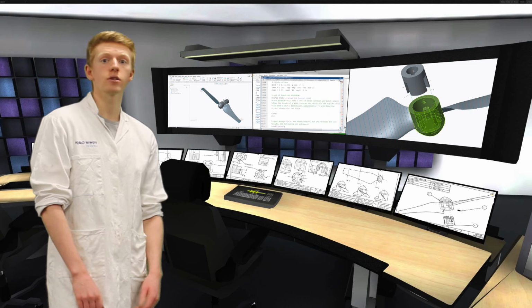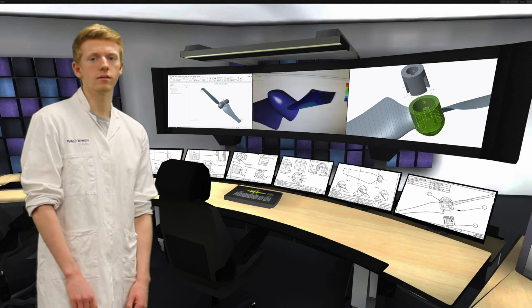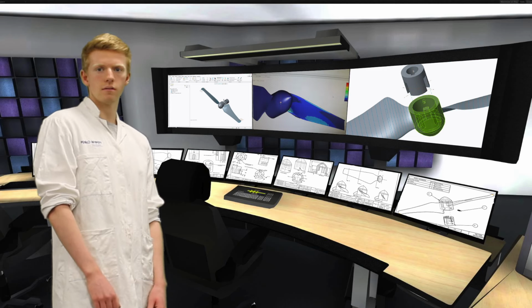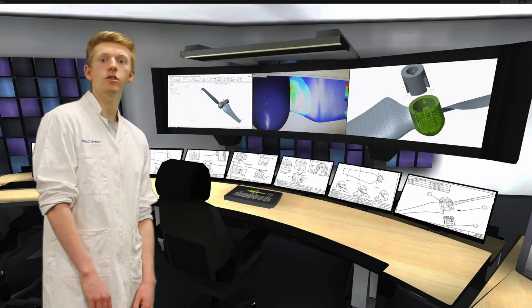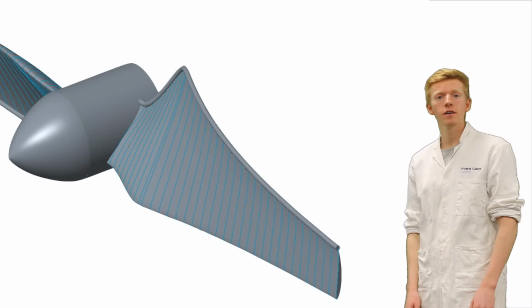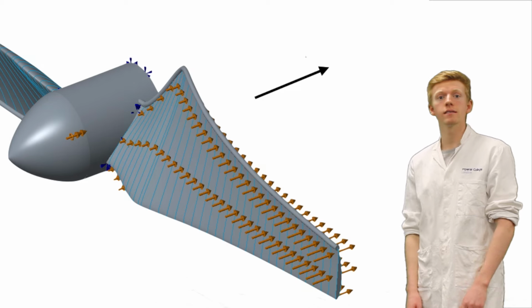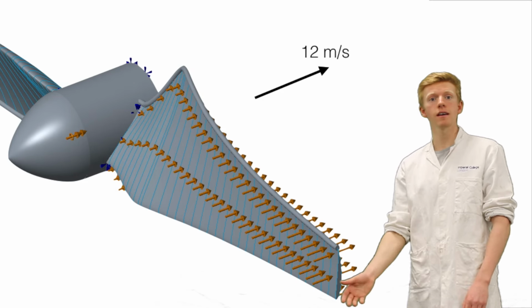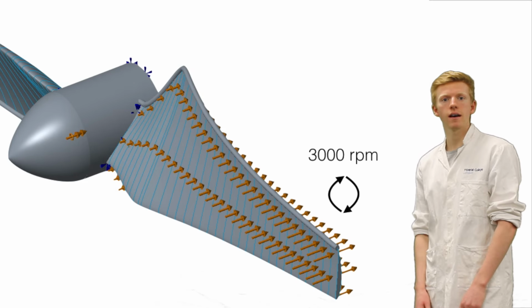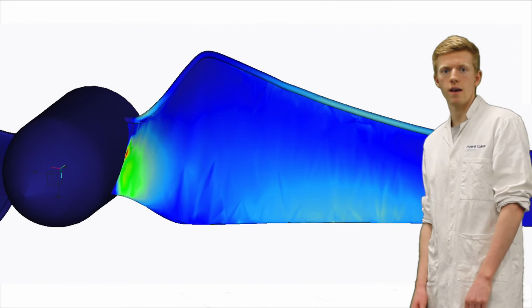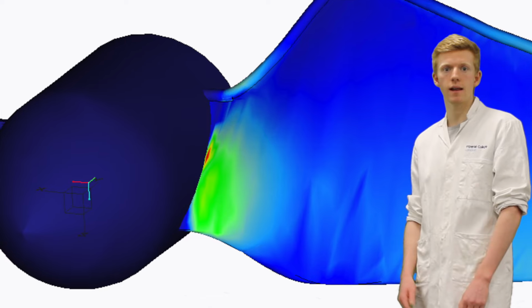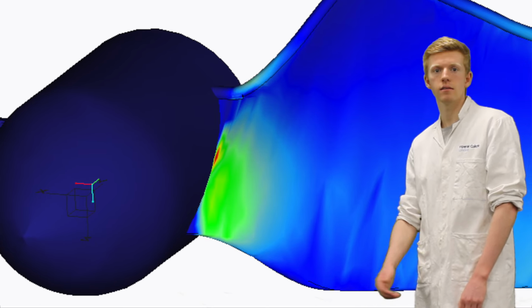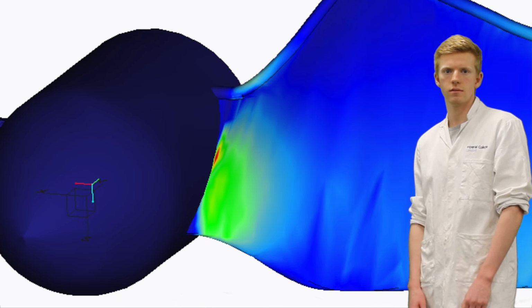However, we deemed the structural integrity of the blade to be of great importance and decided to test it in ANSYS as well. Finite element analysis would give a much more reliable view of the stresses in the blade. Significant loads were placed on the blade in ANSYS. We tested it at the maximum wind velocity of 12 meters per second and the maximum angular velocity of 3,000 revs per minute. It was found the root stress was too close to the failure stress of ABS, and since this method was still approximate and we did not have all the real loads involved in the simulation, we opted not to take the risk and to instead use a thicker airfoil at the root.